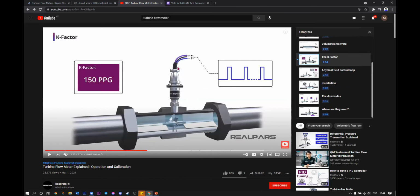If we buy the turbine flow meter, it will come with the K factor, which indicates, like this one, 150 pulses per gallon, which means that the flow rate will be counted using this pulse. The pulse shows 150 pulses per gallon. This is the gallon of water that flows in the turbine flow meter.